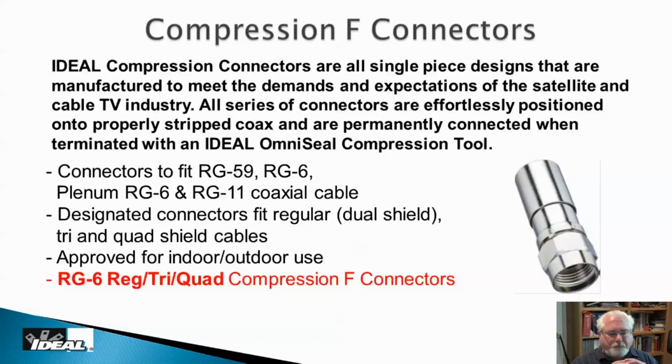Okay. Now, the compression connector we mentioned here, when you look at it, we sell regular RG6 quad. We also sell a universal. And this is an example of the universal. And it can work with regular RG6. It can work with tri-shield coax, which is a foil, a braid, and a foil. And also works with quad, which is full braid, full braid. So, as I said earlier, be aware you might run across some cables that this might have problems with, but as a general rule, it really works pretty good on most manufacturers' cable. So one connector, you don't have to stock multiples of them.